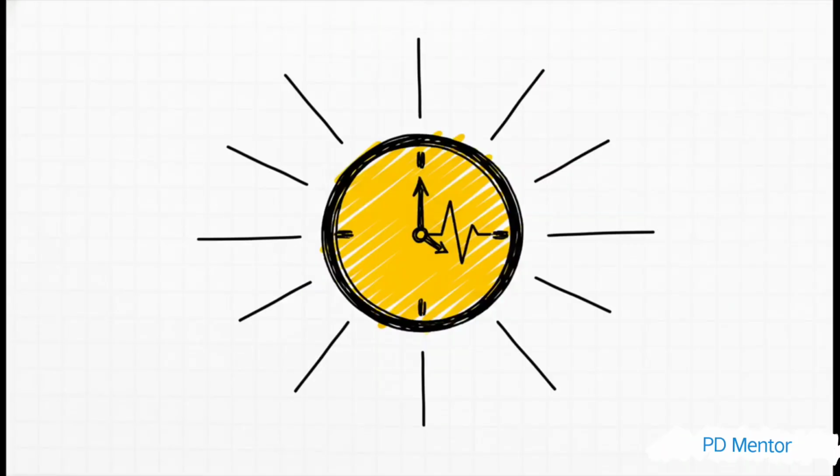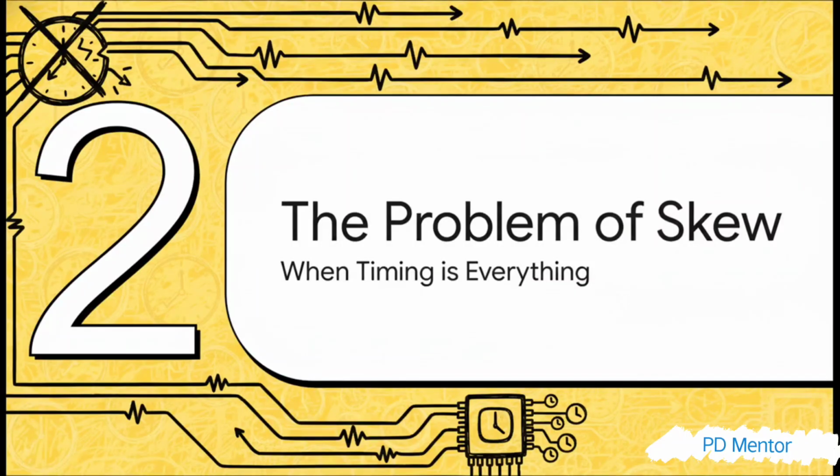Right, so this is where we begin. Just one signal coming from one spot. It sounds simple enough, but this one little fact is the source of a massive physics problem. A problem so big it could make the whole chip completely useless. And that problem, the big bad villain of our story, is something called clock skew. It's just this unavoidable performance-killing thing that happens because, well, signals don't travel instantly. It takes time for an electrical signal to travel down a wire.